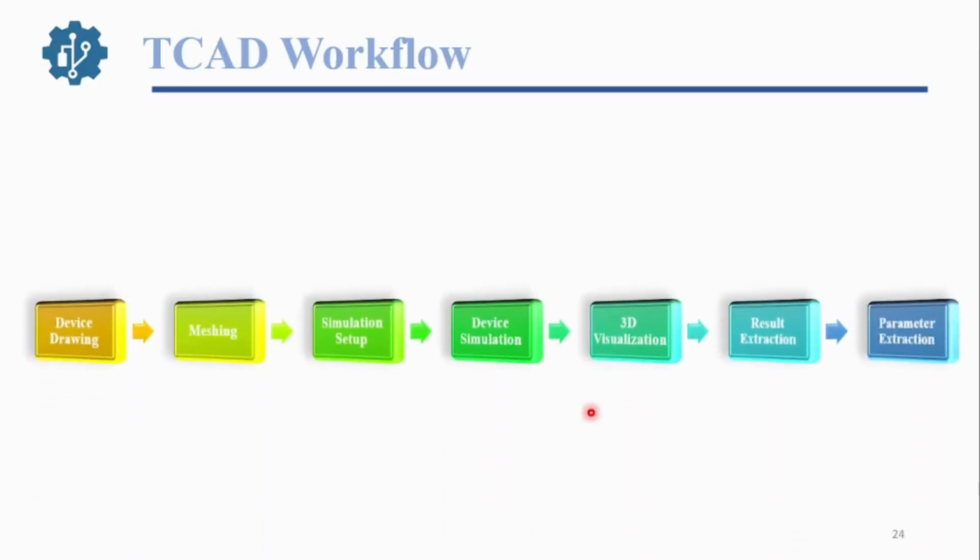And the TCAD tool is basically a virtual environment of the fab. In this tool, you're just creating a single device or a multi-device, or converting a mixed mode simulation, just creating a device and converting it to a circuitry. These are some of the basic steps. You just follow them and create a single device on a TCAD tool, starting with the device drawing. Every step is discussed in detail in the next slides.